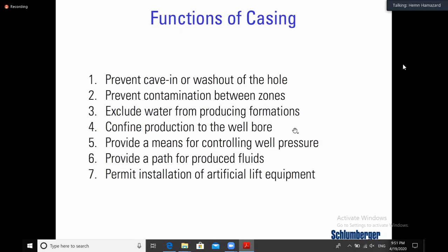If you imagine, it depends on what class of hole you are drilling. If it's exploration, for example, you usually start with a 36-inch hole or 46-inch hole. If you have that big 46-inch hole, it's more than 1 meter. It's about 1.3 meter hole diameter. If you continue the same thing, just imagine all the way to the well TD, which is about 4,000 meters, you cannot have a 1.3 meter hole all the way to 4,000 meters. You need to shrink it one by one.